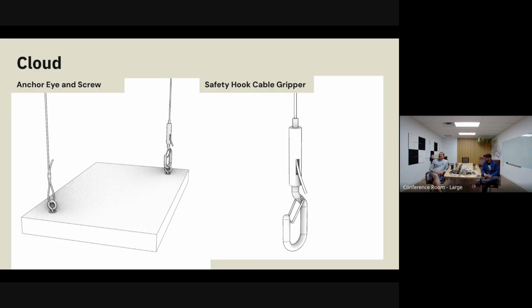At the moment, Amy, I do not have a great solution as an alternative to panel wall. Panel wall is a name brand version of, so to describe it for everybody, an aluminum framing system for panels that is a little bit modular and allows you to keep things nice, straight, and even, and can typically be easier for the contractor to install panels into because it's all gridded out for them. That's just a name brand version of an aluminum reveal system.